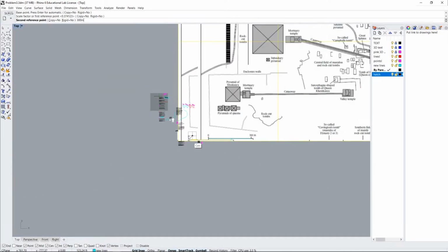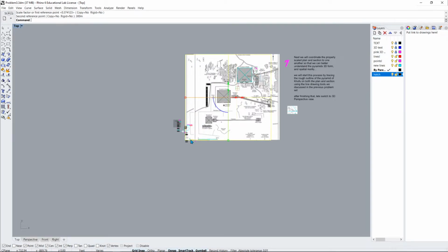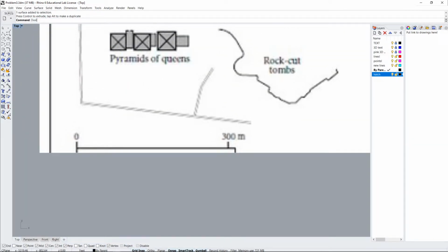And so what it's done is it's made my image the actual size. So if I go in here, sorry, I'm just going to come over here. If I go in here and zoom in and do the command distance, it's going to be approximate because this is, of course, a vectored image. Click here and I click here, holding shift to make my line go straight. I'm going to see that that's 986.5 feet, which is approximately 300 meters.